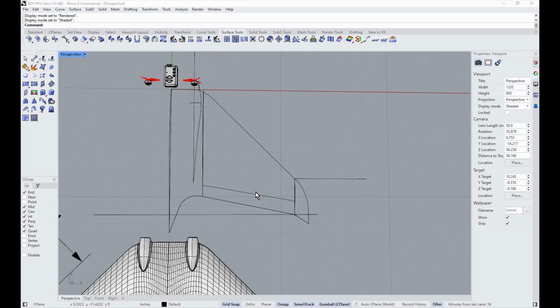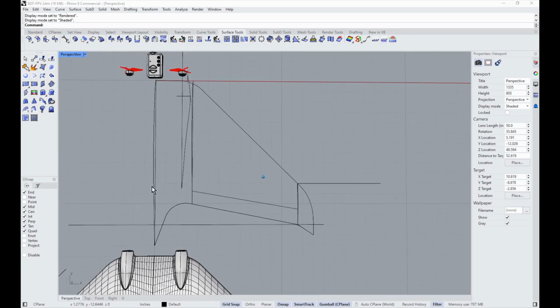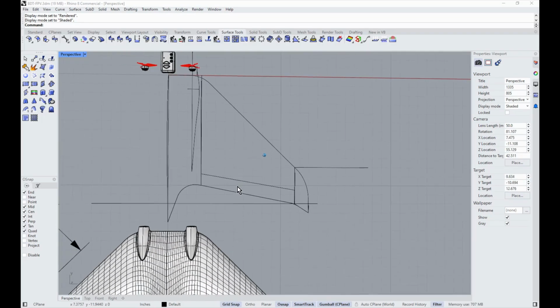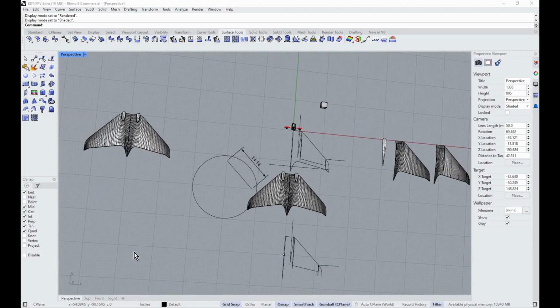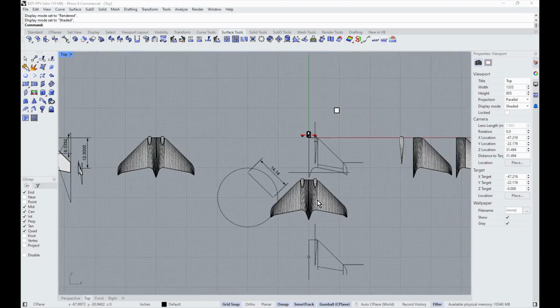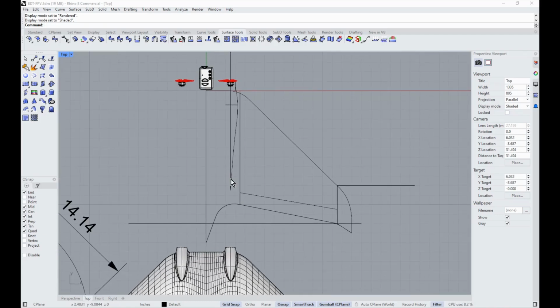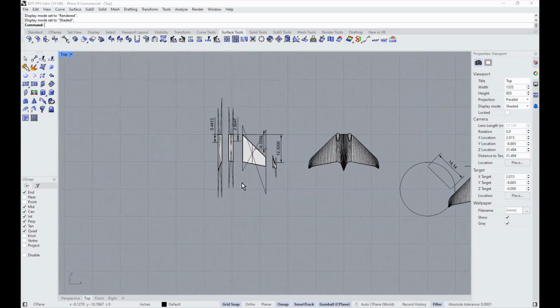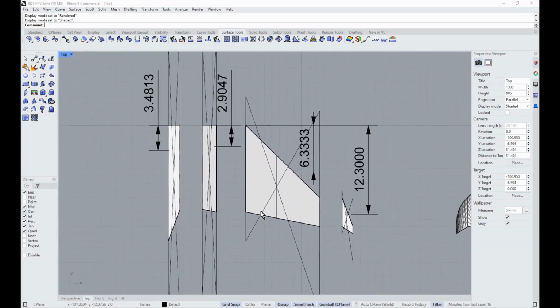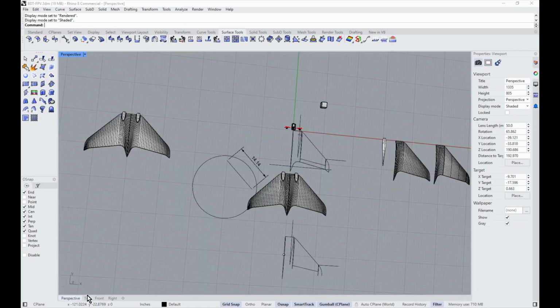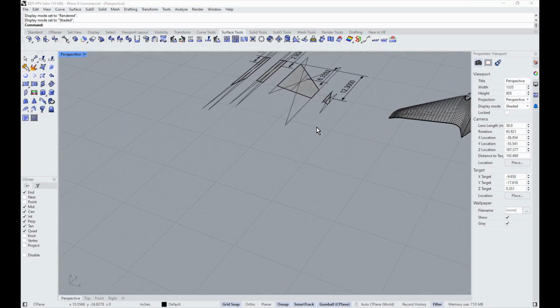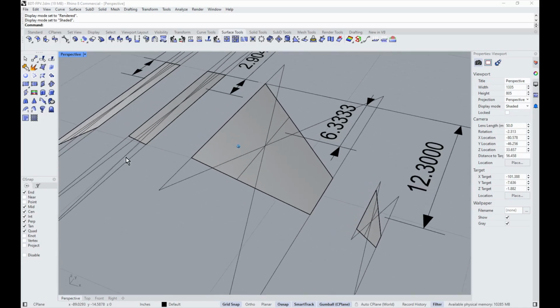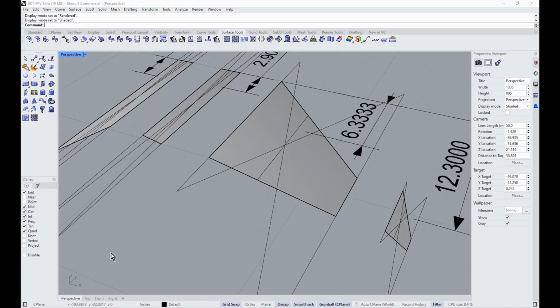So here's the planform shown from the top, and it's broken into several sections. In top view, I actually have it broken into 4 sections with this little crank area turned into 2 individual sections. So those are shown here, and I turned them into an area so I can get a projected flat area for each one. And I simplified them into basically trapezoids.